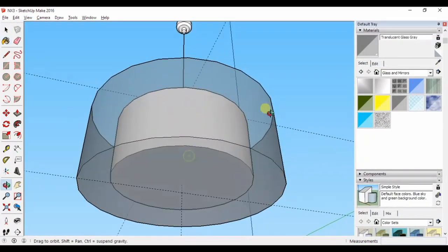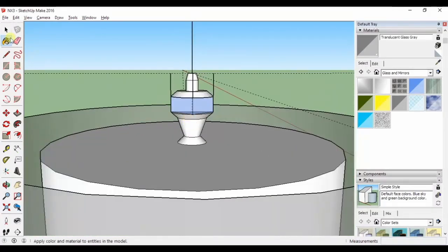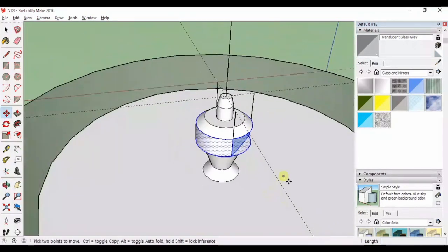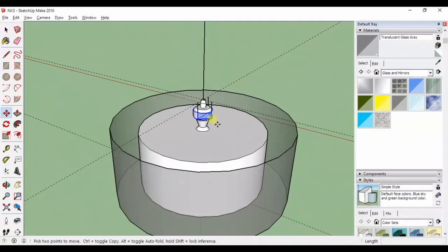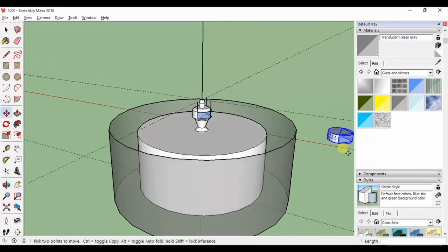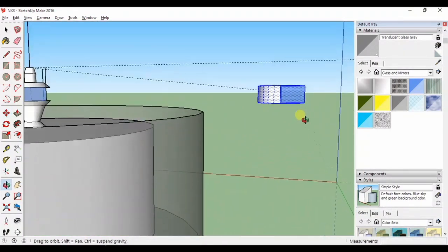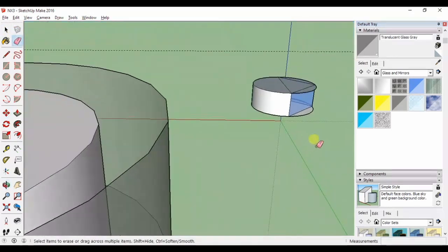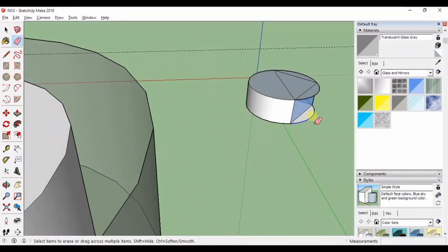For the moving mirror and the fixed mirror, I can make things a bit easier by just copying what I did for the rotating mirror. I'll select everything relevant to the mirror with the Select tool and by holding the Shift key. From here, it's Move tool, hold Control and drag away to get a copy. Notice since I didn't delete my earlier guideline, I can now reuse it to align the new mirror with the rotating mirror a bit better.